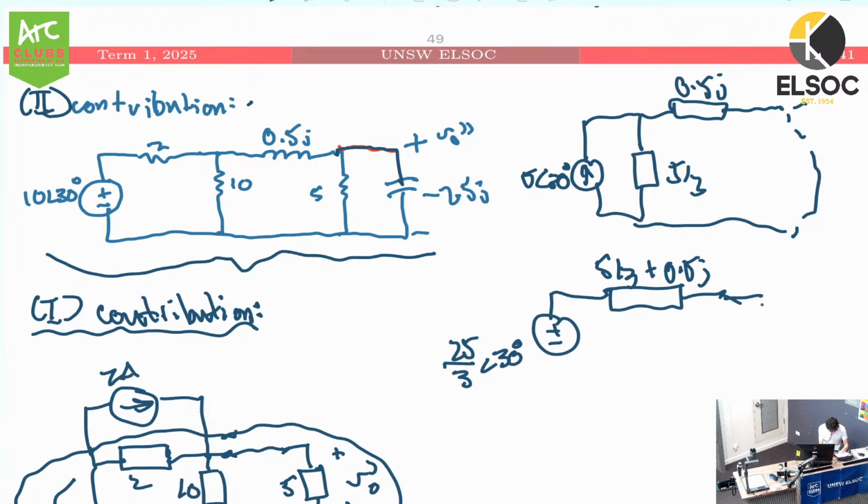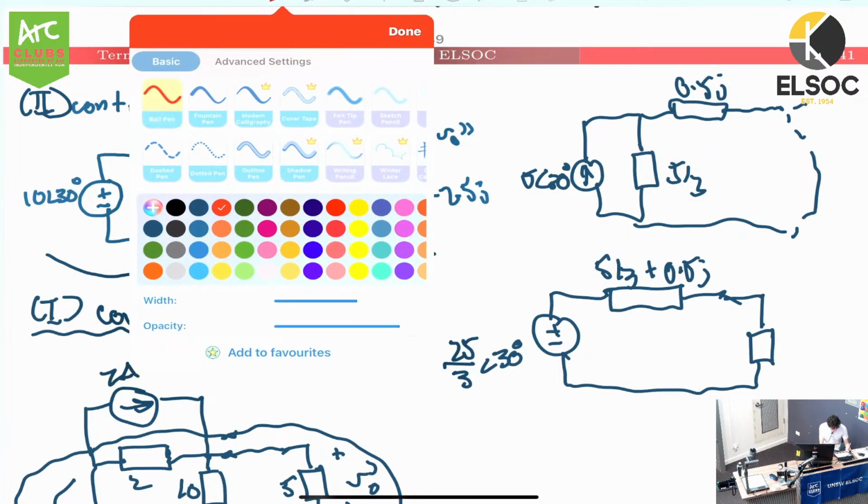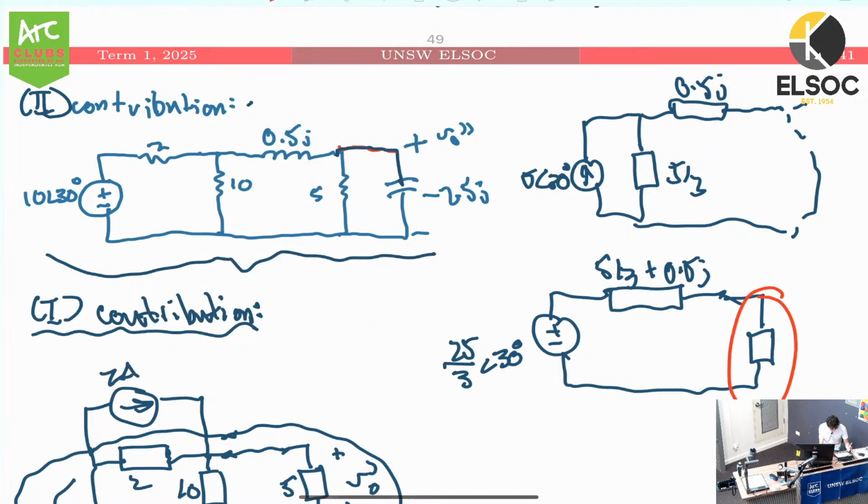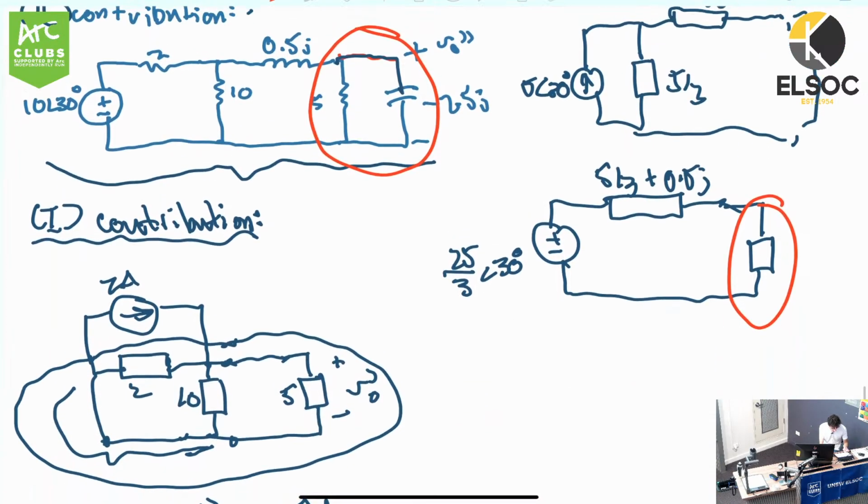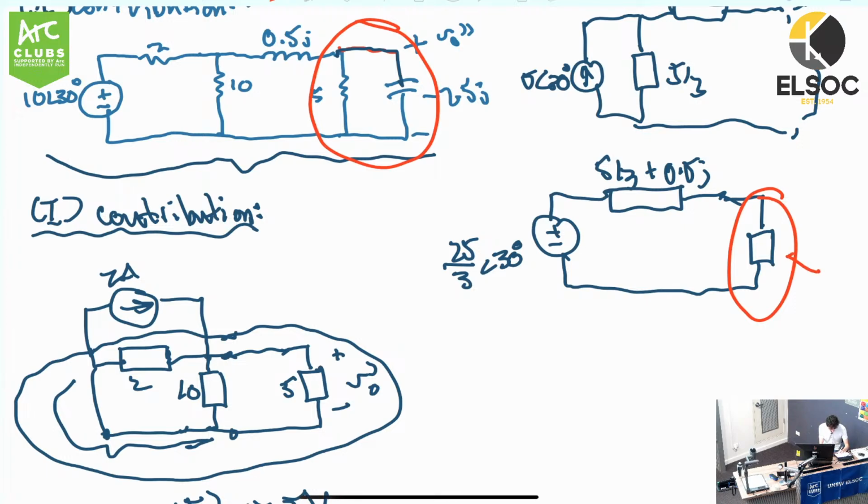And then we'll get the last part of this impedance. Now, we know that this part right here is actually the same as this. So I can just simplify those in parallel. So what I know is that we've got the resistance and we've got the impedance. So we'll call this ZEQ, I guess. And so this will equal 5 parallel negative 2.5j.